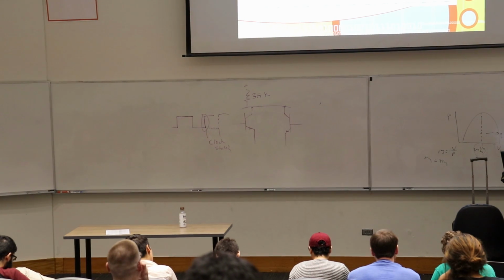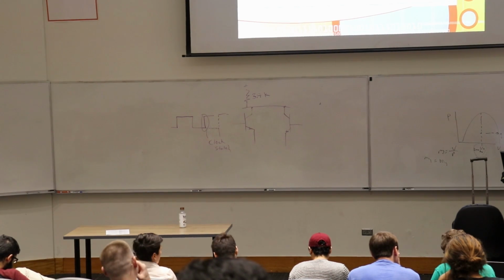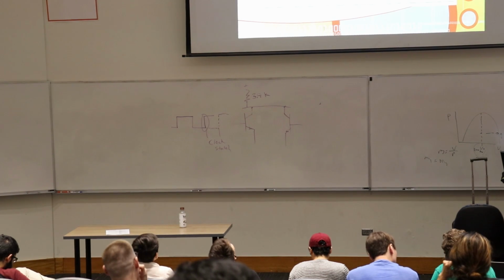So anyway, I'm not going to go through this at great length, but basically you normally load up the byte you want to transmit, and then that byte gets shifted out one bit at a time. So this is a true serial port. The bits go out one bit at a time down a single line.